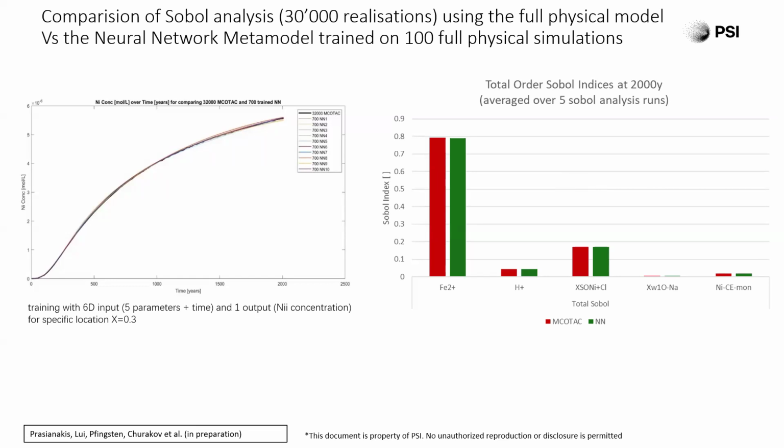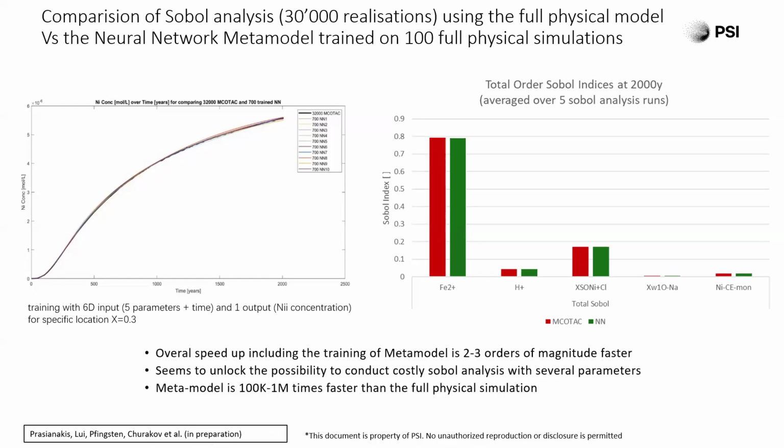And then what you see here as bars is the Sobol index. A high bar means that this parameter is more important than the other parameters. This means that we can now focus our research on identifying these parameters better and constrain our models, or that we have to be careful with these parameters and their influence on the result. Then here we have a speed up of 2 to 3 orders of magnitude. And this is, of course, an envelope to the previous ones, right? I mean, this is adding another layer of acceleration if we are interested in inverse modeling, in optimization, or in model parameterization.